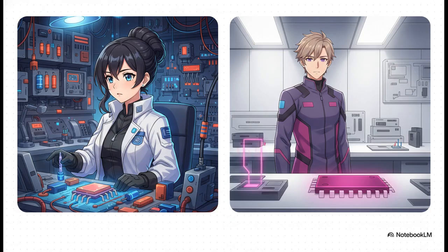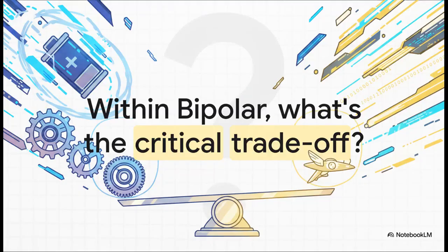Think of them like a muscle car. Then you have the unipolar families, like CMOS, which are built using only one type of component, MOSFETs. This lets you pack an insane number of them into a tiny space and use way less power. That's why they're everywhere today. All right, let's say your project needs the speed and power of a bipolar family. You're not done choosing yet.